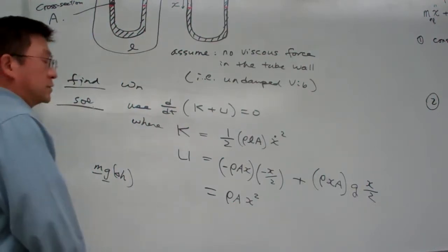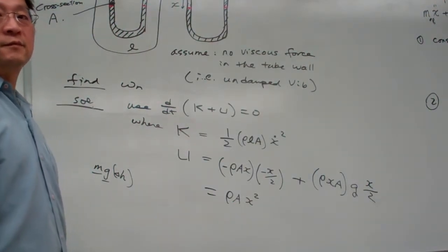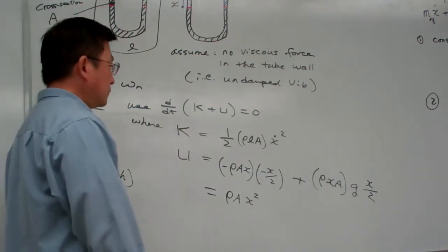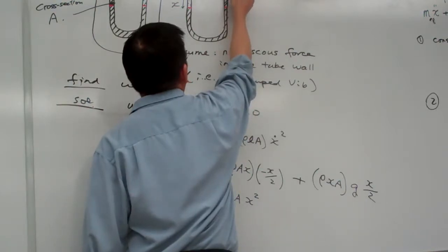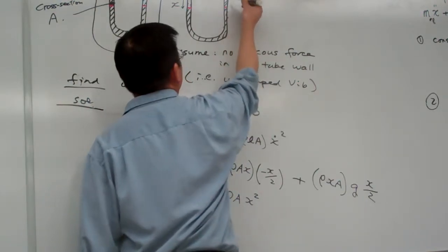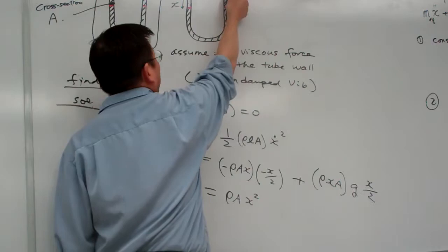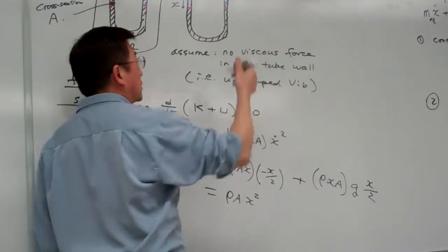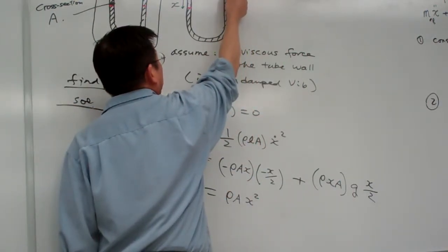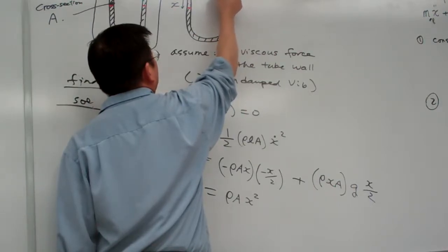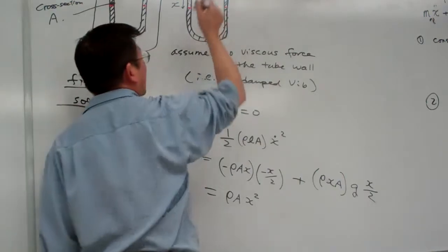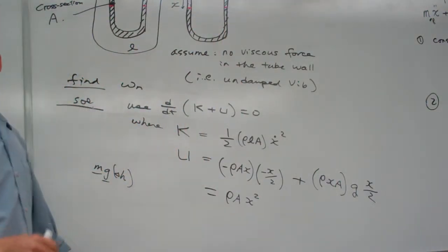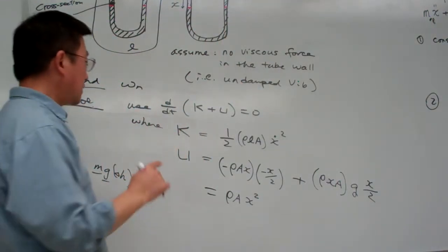Okay. Yes? I think you said this a couple times, but I missed it. Why is it X over 2? Yes. For this one, it is because this is a uniform mass, uniformly distributed. So the equivalent change in the potential is simply we take the center of the mass there, and this is X over 2. We simply take the whole mass, multiply with g, multiply with the equivalent height. Okay, so that's taken care of.